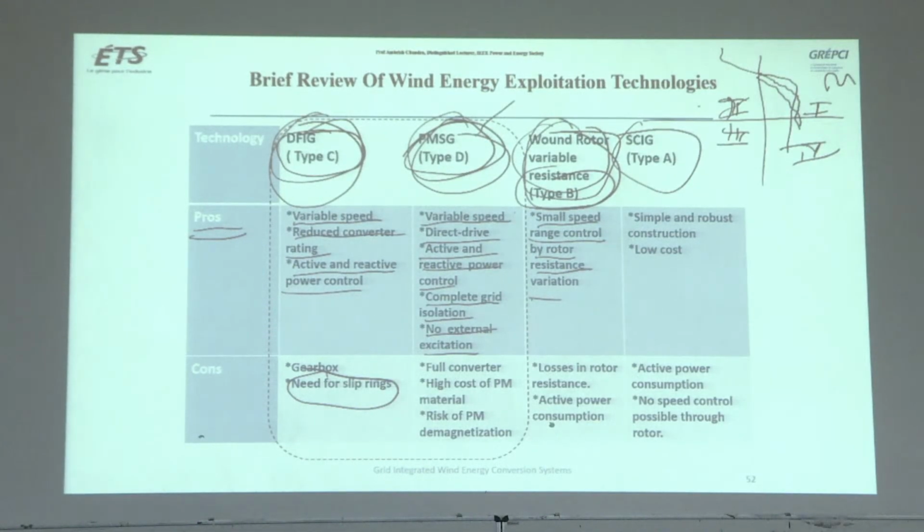This is motor, generator. So by varying the resistance in the rotor circuit, basically you are changing the speed. This is what it is basically, wound rotor you are putting, because maximum torque, this is the advantage, right? You might have studied this in induction motors. Basically, you have maximum torque here.